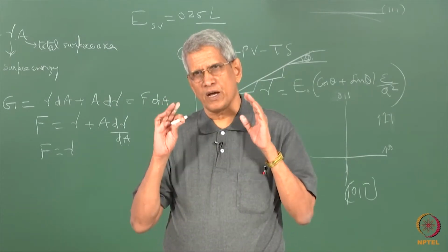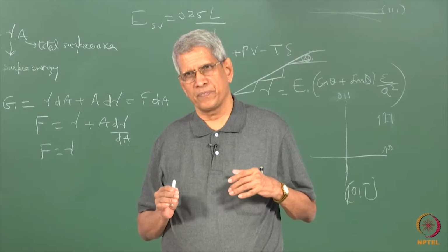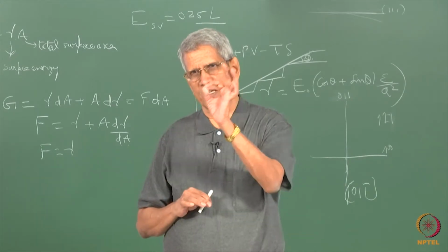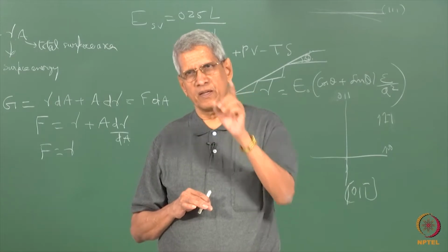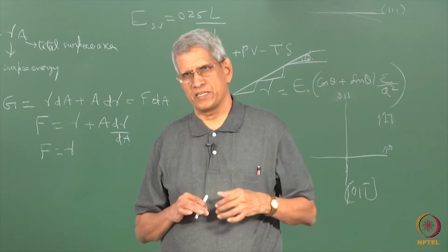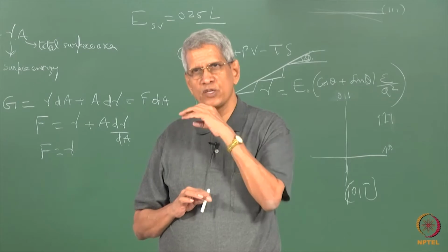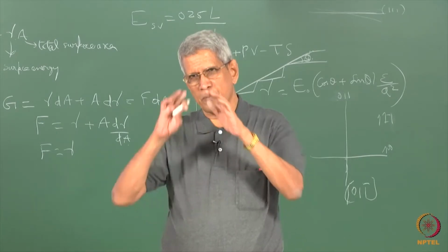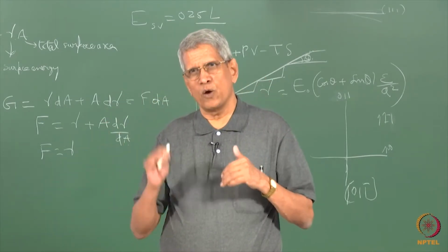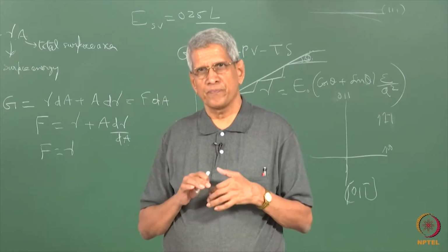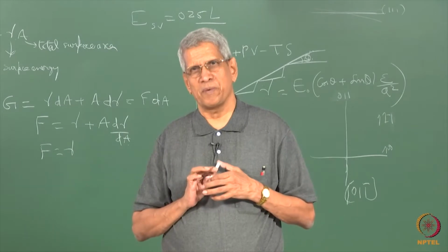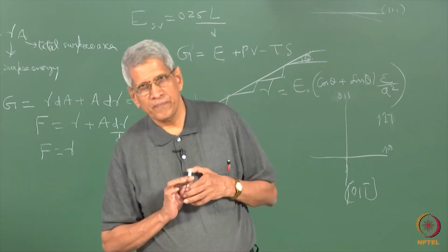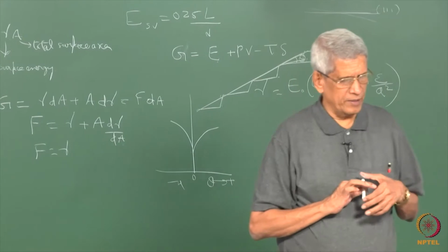Generally the voids assume a faceted shape, whereas if it is a gas inside, that applies a uniform pressure, it never takes a faceted shape, it takes a spherical shape. This is used as one of the indications. That means that internally it tries to take the shape of a void so that the total surface energy is minimum. Correct?